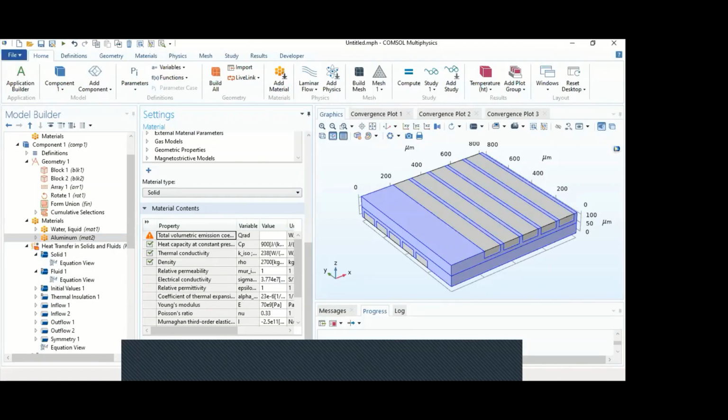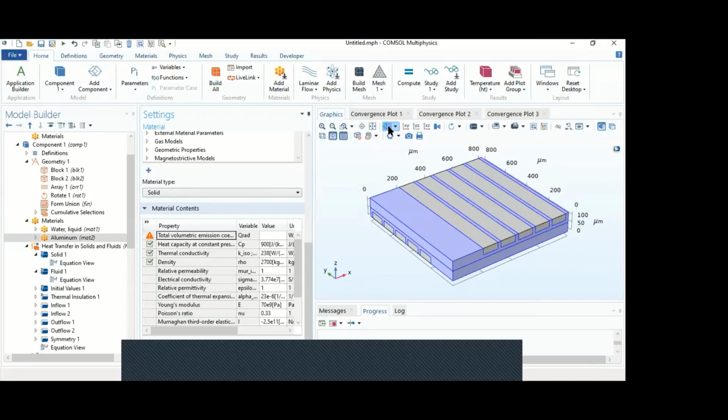If you look at the temperature profile, for example, in this case, you can find a rough transition between one temperature to another, or one value to another. If you increase the mesh element resolution or decrease the size, it will produce a better plot, but it will take much more time. So it's basically depending on the user's experience and best case scenarios, or best case experiences from other users.